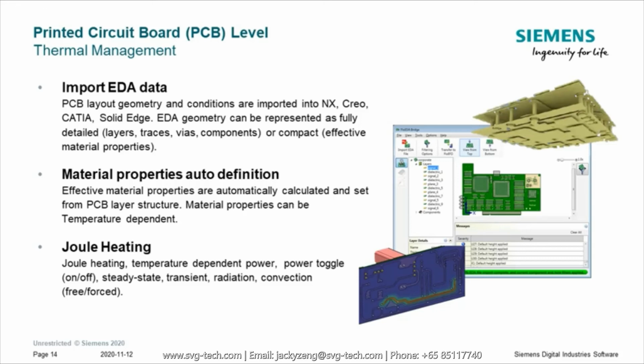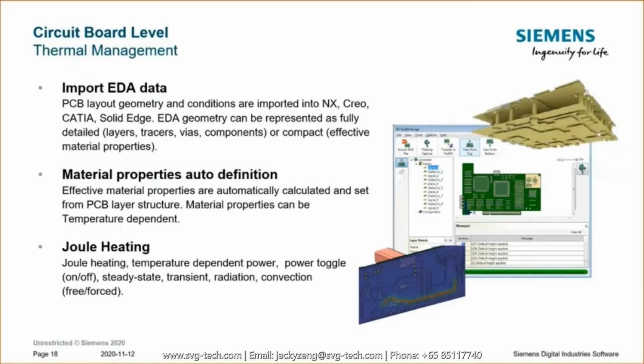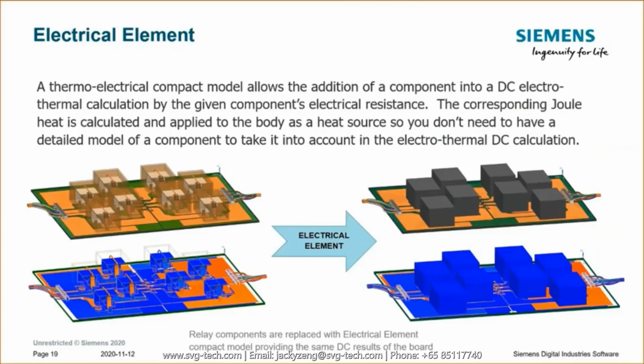Probably the most interesting and powerful one is the one that Adil showed in the demo, which is that newer material map option, the smart PCB. It essentially creates a massive thermal network using more of a 1D network style approach to model all the copper distribution in the board. And you get this great balance between a lot of accuracy through the detail without the overhead of classic 3D ways of trying to represent all that geometry. So different options with respect to your board modeling.